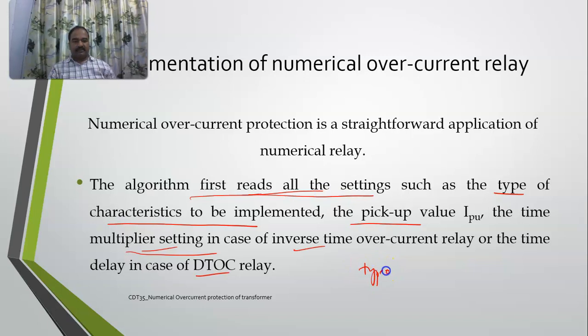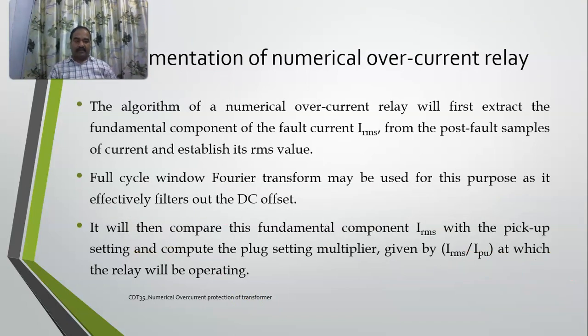The type of characteristics. If it is inverse characteristics, you must know the time multiplier setting. If it is a definite time overcurrent relay, you must know the time delay. And also the per unit pickup value. These you must read before you start implementing.